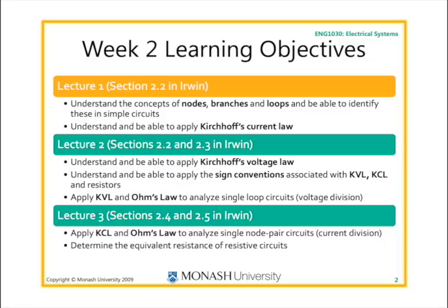The 3 nodes are, there's one up the top, and that includes anything that's connected to that point only by wire. So it includes all of that. That is one node. It is not 3 different nodes or 4. That's one node. There's 2 down the bottom here. You know, all of that, that's 2. So really, there's only this one as a third one.